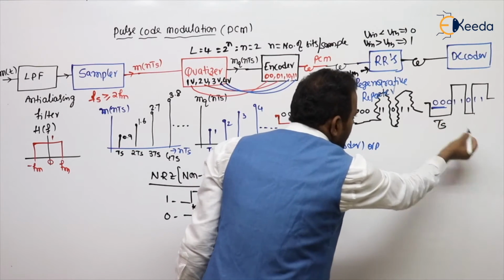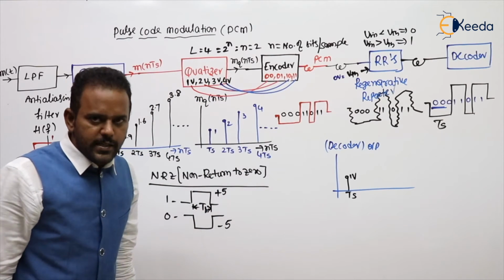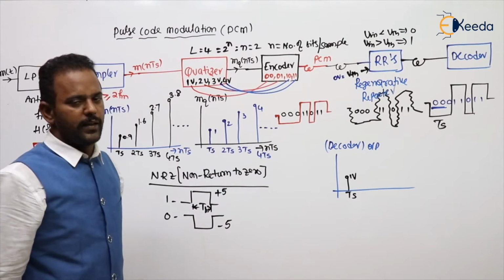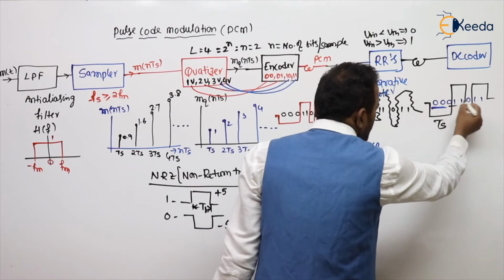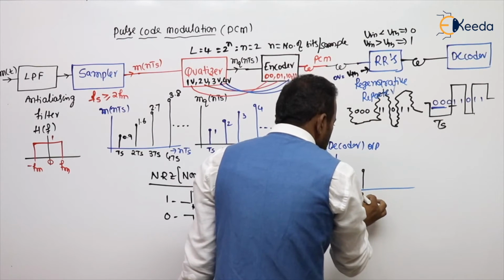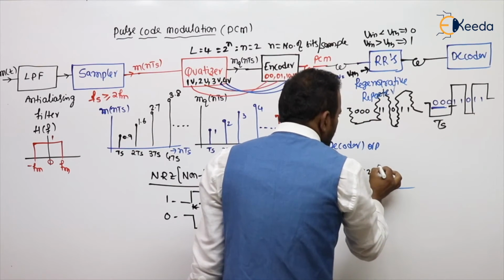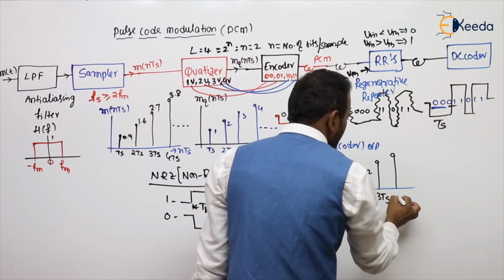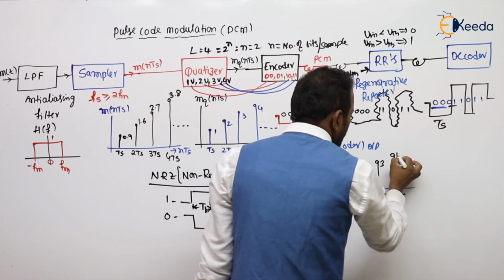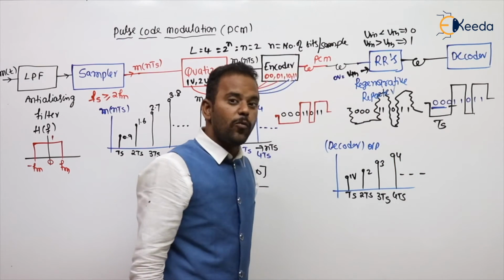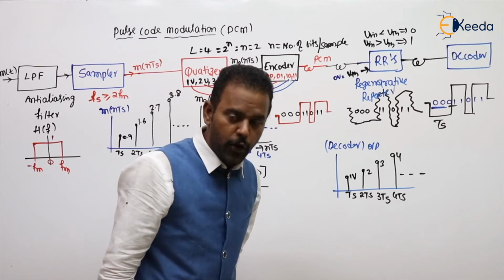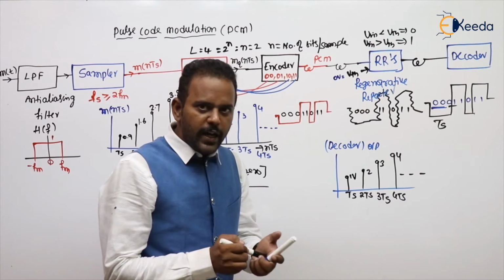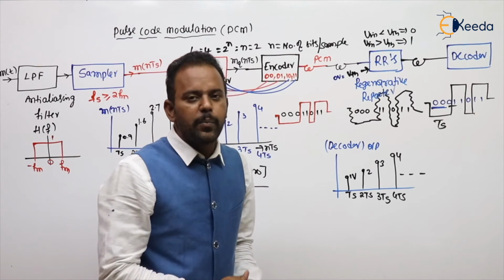This will maintain the exact duration of Ts. That we will maintain, don't bother. Next, 0 1 means 2 volt. Next 1 0, 3 volt. Exactly inverse mapping, and so on. There is a 1-to-1 unique mapping, I already told. So the corresponding voltages will be reproduced.